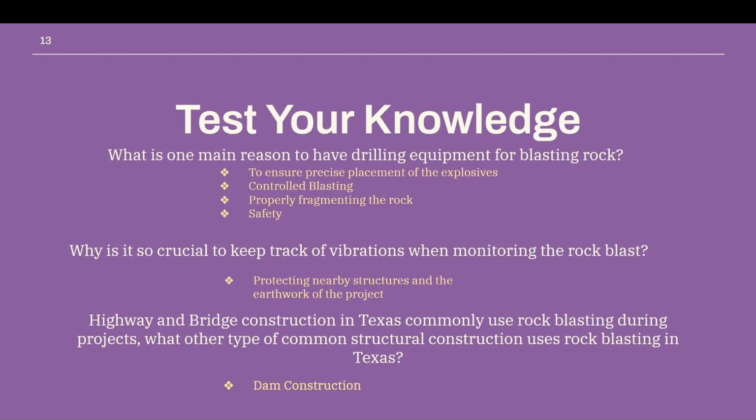Here are the answers. The main reasons to have drilling equipment for blasting rock are to ensure precise placement of the explosives, controlled blasting, properly fragmenting the rock, and safety. Why is it so crucial to keep track of vibrations when monitoring the rock blast? To protect nearby structures and the earthwork of the project. What other type of common structural construction uses rock blasting in Texas? Dam construction.